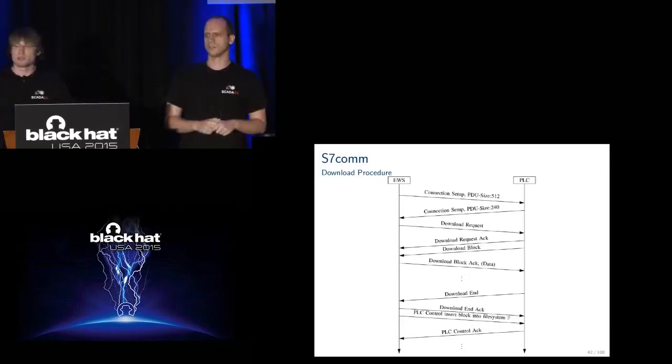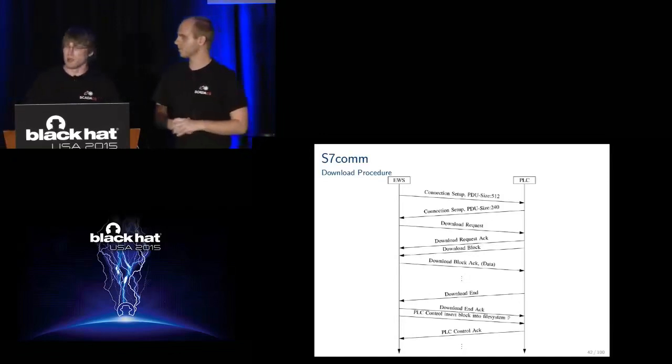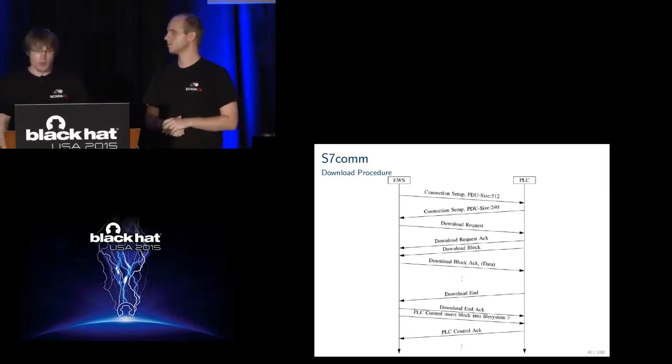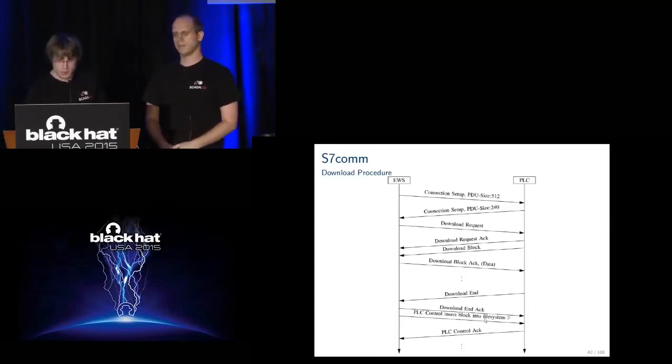And even if you send a large block to the PLC, as we see here in the sequence diagram, it does not actually overwrite the original block. Just when you call this insert function, then the actual block is overwritten. So it's a pretty fast operation, and you probably do not disturb the PLC.